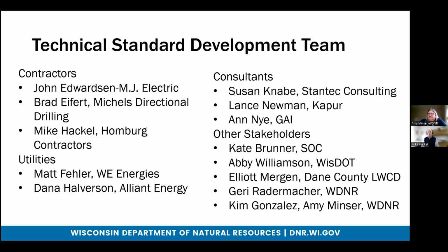They would be essentially working for either the design team or the contractor. And as far as the question for reporting, you've got 24 hours to report an IR based on the standard. The required information to provide at that time is the amount of fluid that was lost or gained and the amount of fluid that was recovered during the response.